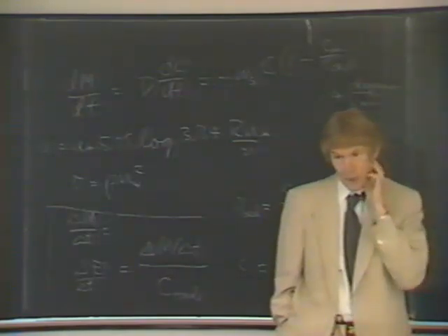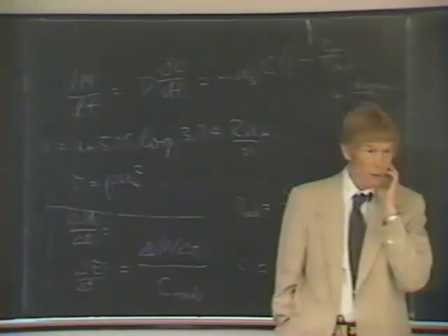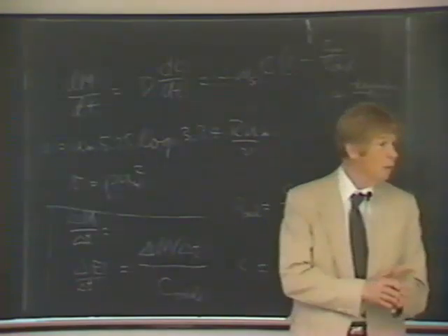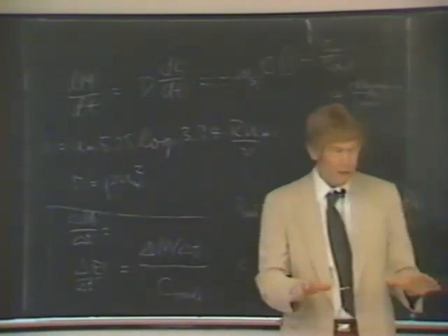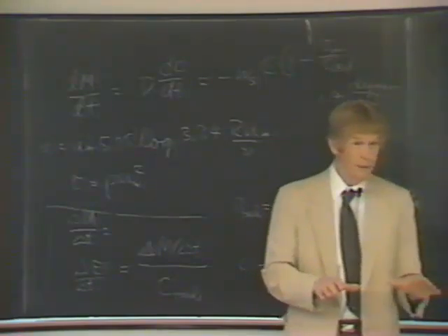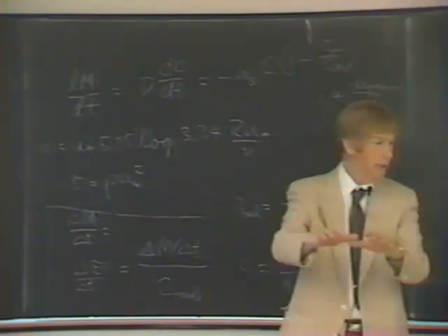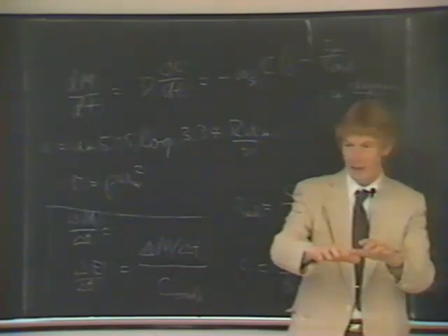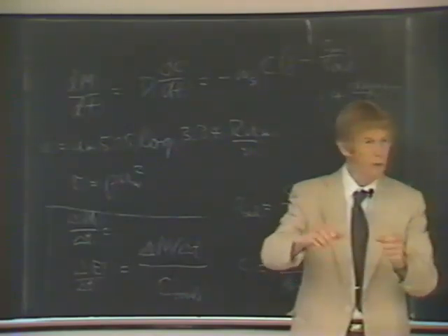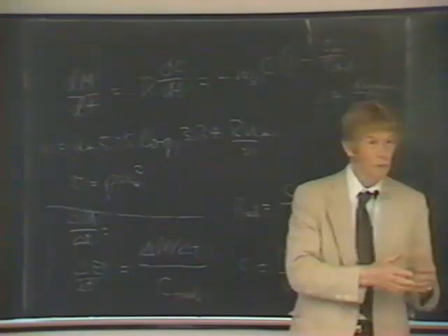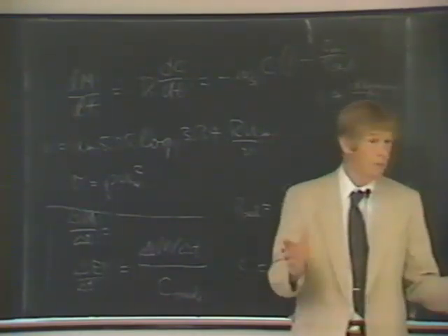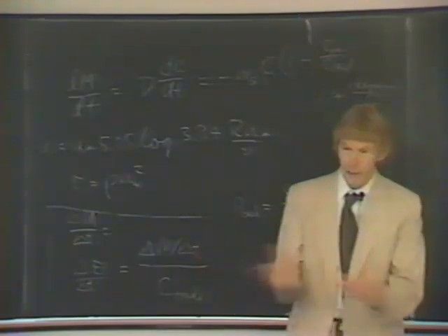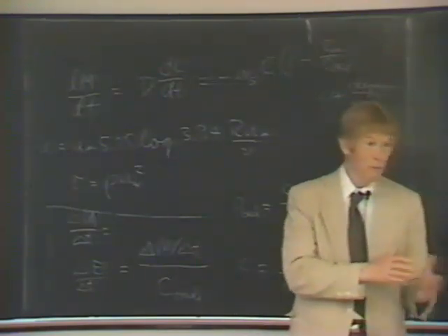The next step is to look at what opportunities there are. If there's no harbor and you want to locate one, and you're able to locate it, which rarely occurs, by the way, then you can find a place where there's very little sediment in motion, or where the scouring currents will keep it moving through, or places that are ideal. That would be the best solution. If we could go back and rebuild all our harbors, we could do a far better job than has been done.